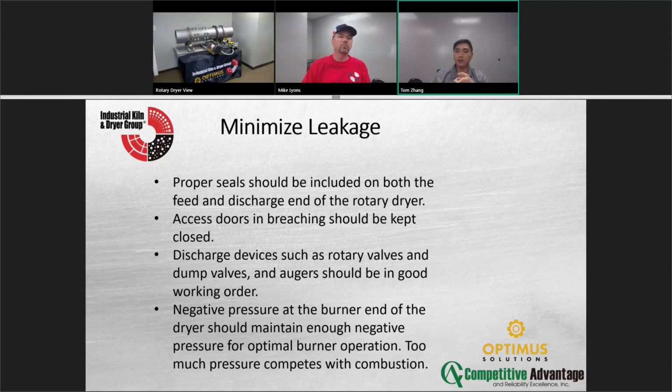If your seals are damaged on the next shutdown, especially if you have leaf seals, you can just go ahead and change them out. If you have material falling, that typically tells me that you have a material movement issue, how you move that material. You can have buildup. There's several things that could cause that. But it's not the seals.